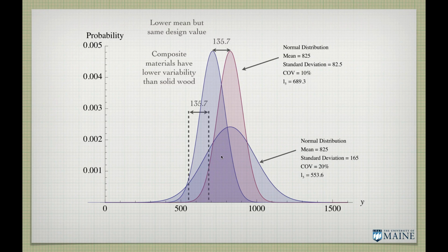That really wasn't select structural, that was number 1, because the graders missed. When you're visually grading, you make mistakes every so often. Actually, the standard allows them to be wrong 5% of the time. Or that's a reason why you might go with non-destructively tested lumber to automate that process and get rid of a couple bad actors.